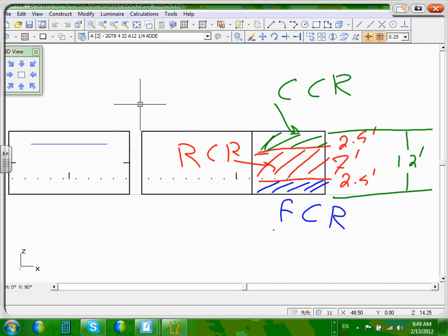Now, Rob, the only cavity that I want you to pay attention to that is used for the calculation is the room cavity ratio, the red, because I care less about what's happening above the suspended ceiling, or even if you don't have a suspended ceiling, you suspend the fixture. Above the fixture, I care less to see what's going on for the most part. Number 2, I care less about what's going on in the floor, because I would never lay on my tummy here and do my work at Dunwoody, laying on my tummy on the floor.